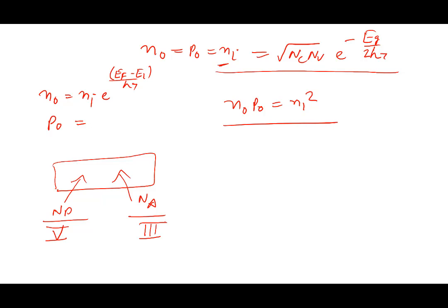So you have achieved some control over your semiconductor. You can increase the number of electrons and make it much larger than the number of holes, or you can make the number of holes much larger than the number of electrons. I can add impurities and alter the amount of electrons and the amount of holes. Doping is important. Ability to alter.